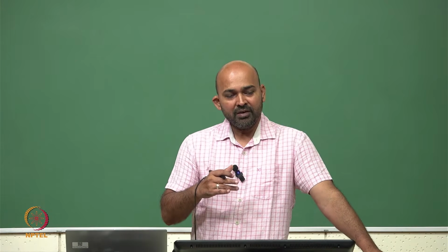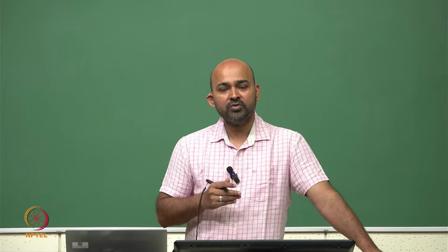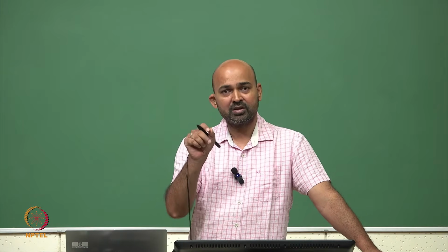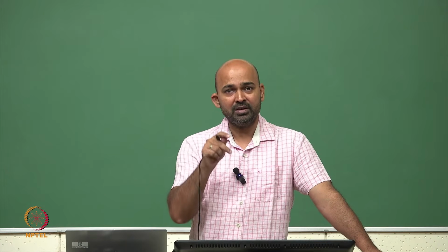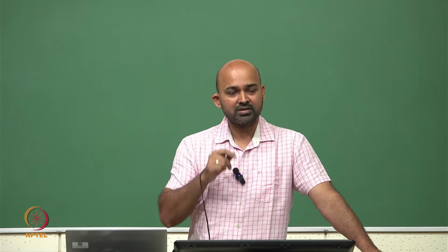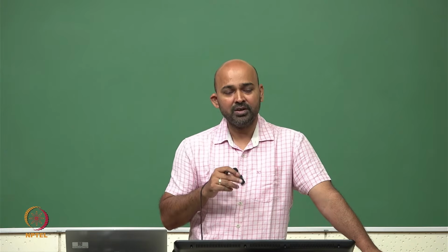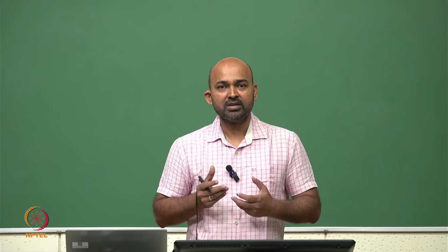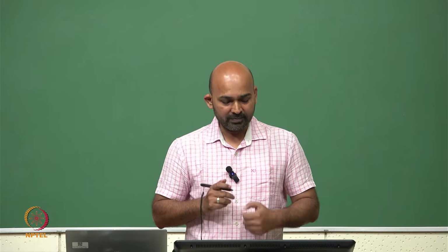So we actually have 4 types of DC sweep which we can specify. Instead of the linear sweep, we can use the drop down in that example where we chose linear sweep. There are 3 other types of sweep which we can use to simulate our circuit. So we have 4 types of DC sweeps in our SPICE software.